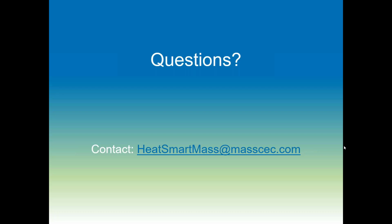Another question that came up is, does our climate need cold climate heat pumps? So in short, the answer that the state has come up with is yes. In the Massachusetts climate, if we're targeting heating, the performance of an air source heat pump tends to drop off significantly once it gets down to, say, 30 degrees.